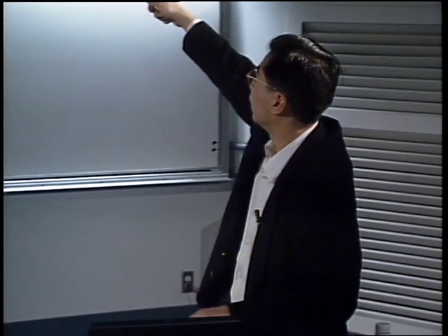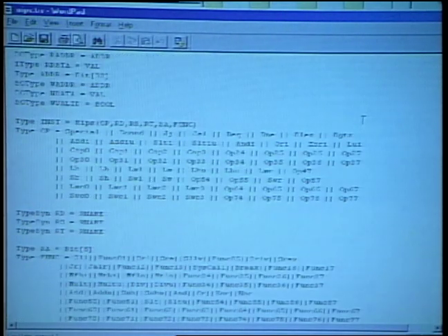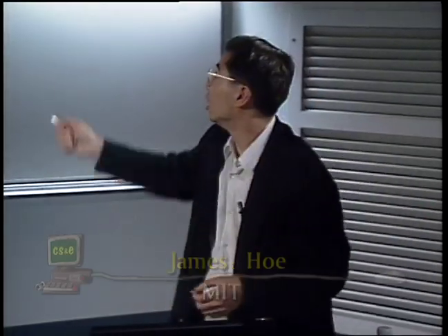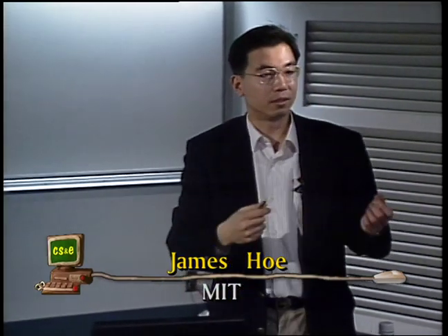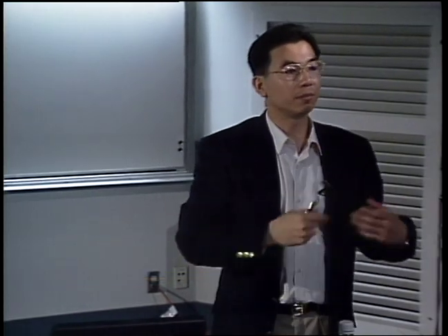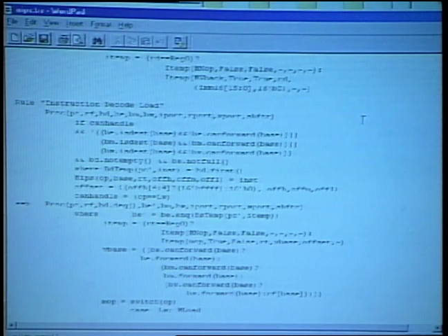And we can go ahead and define the register names. And here we're defining the ISA. Once we have captured the state, described the state of the processor, we can describe the behavior or the operations in different pipeline stages. Different operations for different pipeline stages. Here in the decode stage, we use different rules to describe the decoding of different instruction types in the MIPS ISA.